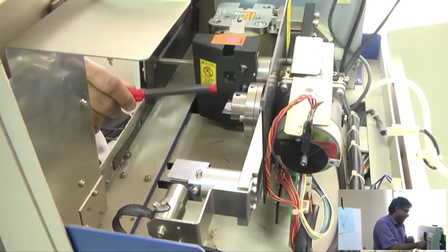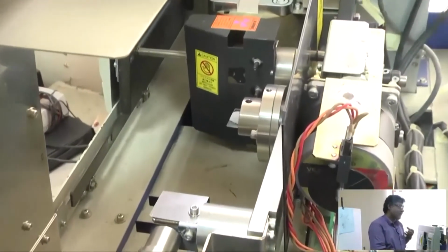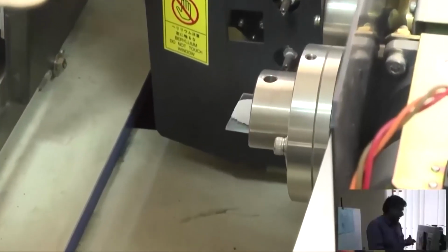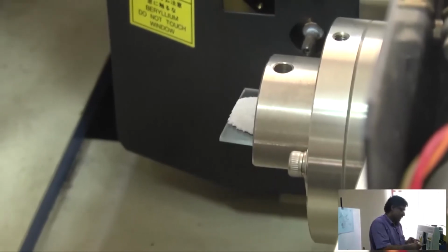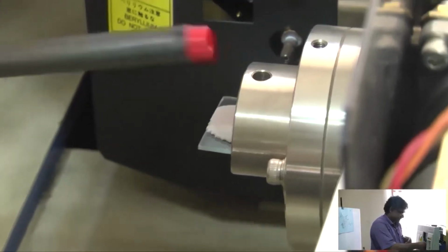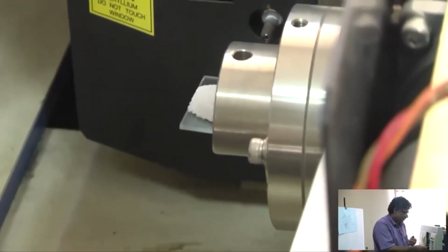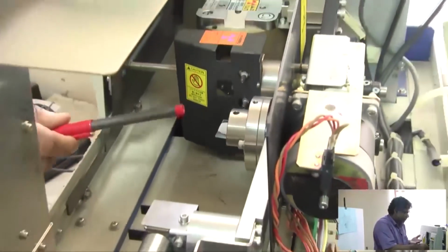Here I have taken aluminum sample powder. Sometimes any other sample in powder form we have to take. This geometry is suitable for the powder method only. In a better diffractometer, where both rotation of the sample as well as rotation of the detector are available, we can study thin film or bulk material.